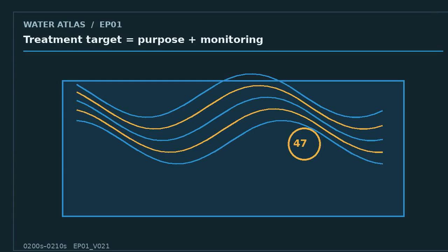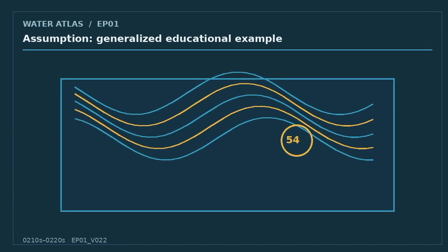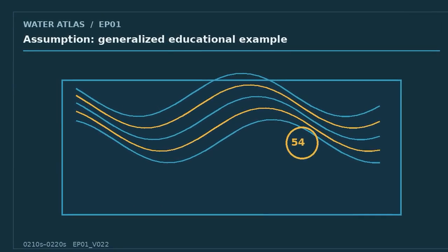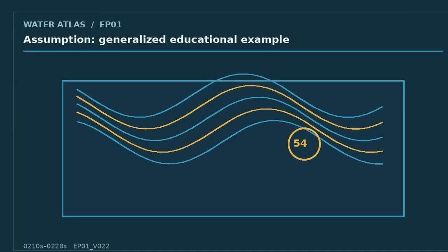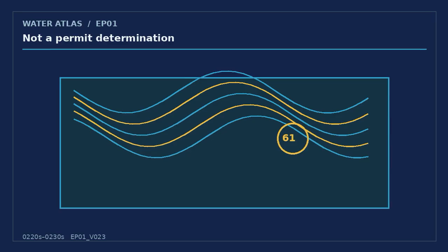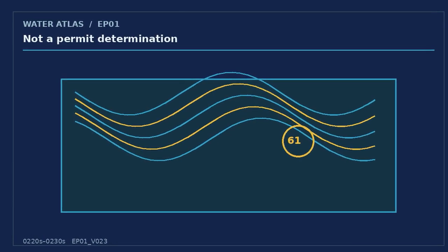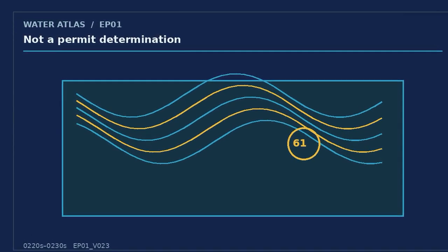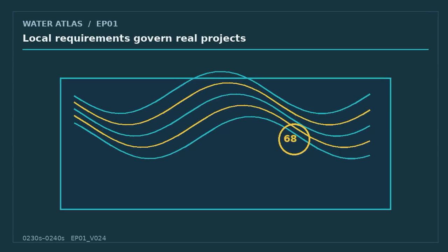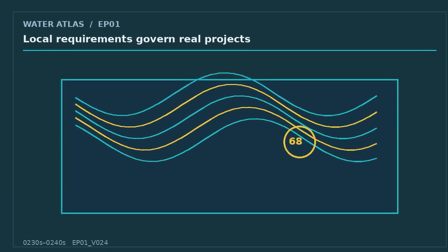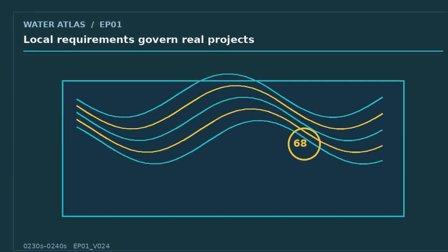At the plant entrance, the headworks protects everything downstream. Coarse screens remove rags, wipes, plastics, and other debris that can jam pumps, block channels, damage aeration equipment, or create unsafe maintenance conditions. Grit removal targets dense inorganic particles, such as sand and small gravel, that settle quickly and can abrade mechanical equipment. These steps do not make the water clean. Their job is to protect the treatment process, stabilize hydraulics, and keep avoidable solids out of later basins.